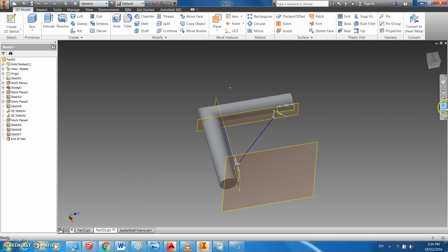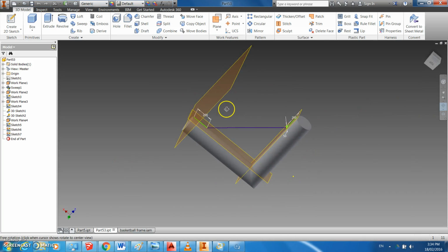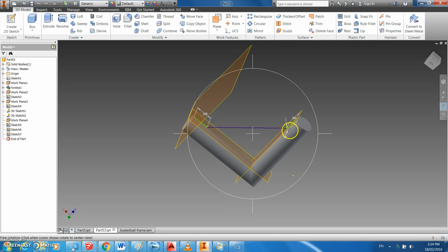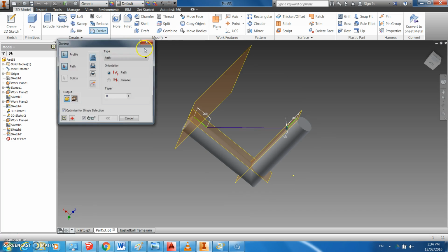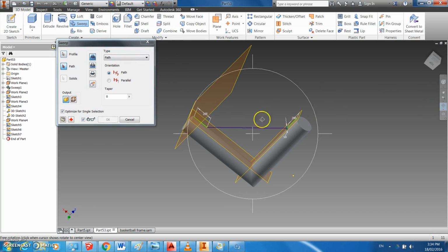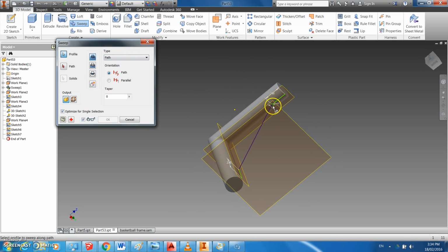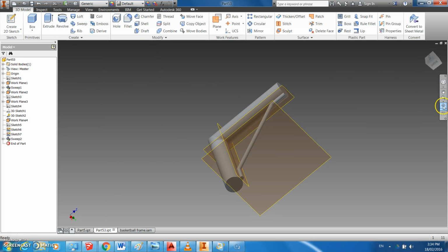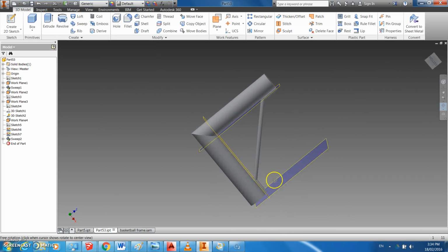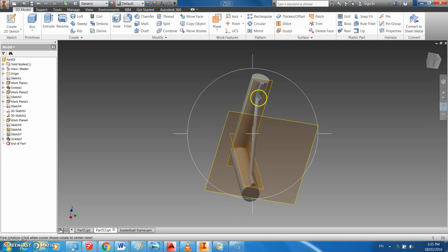Back again. Now as you can see, I've got 200 on each of the two planes that we want. Now if I was to just sweep along those lines, so use the sweep function, spin that around, and highlight the profile I'm looking for, and then the path, you'd find that if I pressed OK there, what's happened is not only have we got the frame running between at 45, but also joining on to the top and the bottom.